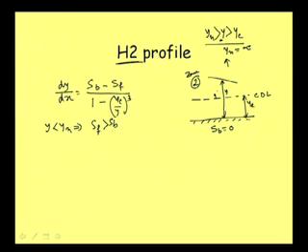Well, now from this point, in case of horizontal flow, horizontal bed, in this case again we have SB equal to 0. So, in the expression dy/dx, SB is 0 minus SF. SF is greater than SB, so SF will have to be positive, because SB is equal to 0. So, minus some positive term means this becomes negative.